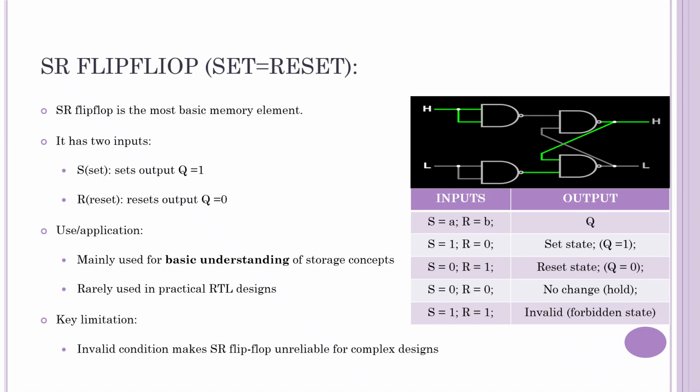That's why it's called a memory element. But here's the catch. When both S and R are 1, it enters an invalid or forbidden state. And because of this limitation, SR flip-flops are rarely used in complex modern designs. Still, it's super important because it helps us understand how memory works at the most fundamental level.